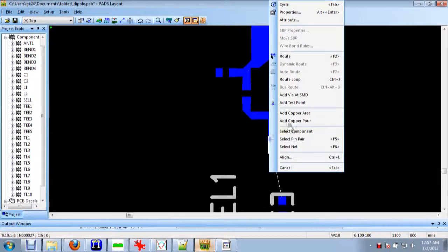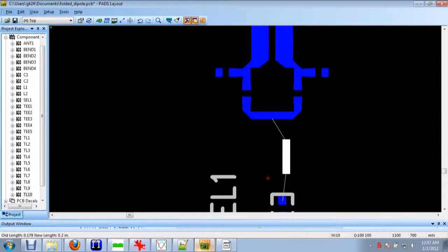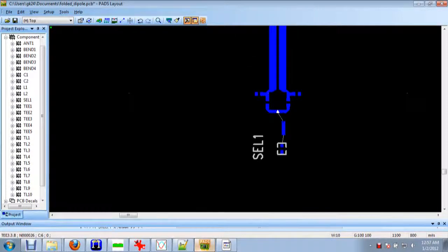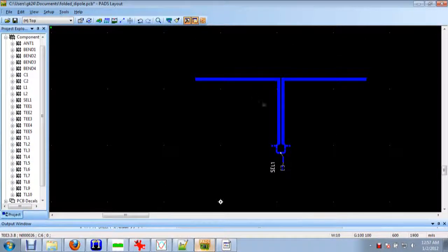So if I have a component like this microstrip line, what I need is to define the two pieces of metal that make this up, the connection point where this is going to want to attach, and then some vector. So for this part of the T-junction, I have a connection point here and a vector that points out this way that needs to match up with this connection point and a vector that points up that way.